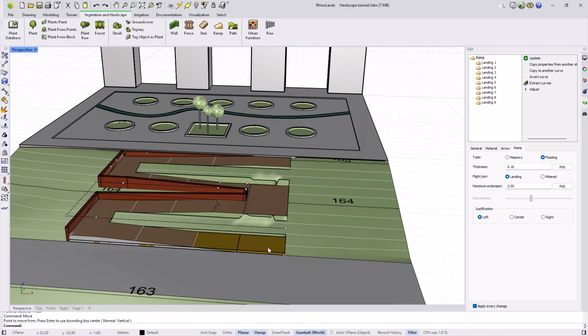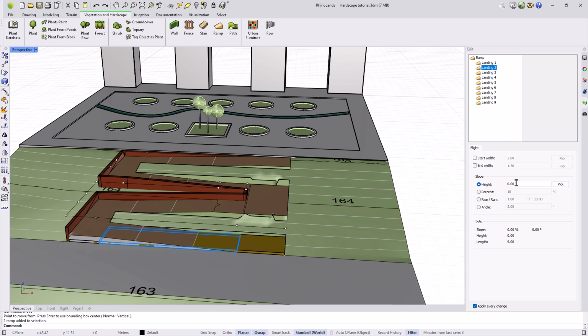When selected, the different segments obtained as a result of the created polyline are automatically listed. I alternately select to slope those segments that match the terrain's slopes. I am going to set a height for these of 0.48, which is the same value we used on the terrain. And so it fits perfectly on it.